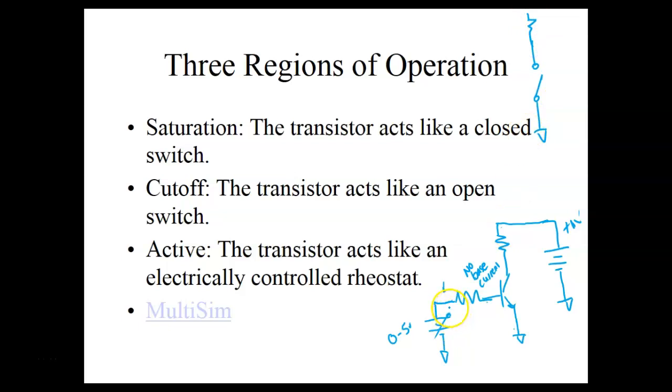Or if the voltage we get on this side is not enough to get, if it's silicon, approximately 7/10 of a volt right there. So I'll start off at 0 volts. If I put 0 volts, the transistor will be cut off: 0, 0.1, 0.2, 0.3, 0.4, 0.5. Then when we get around 0.5, 0.6, 0.7, that's going to forward bias this and we'll have current. But right now, let's just use 0.